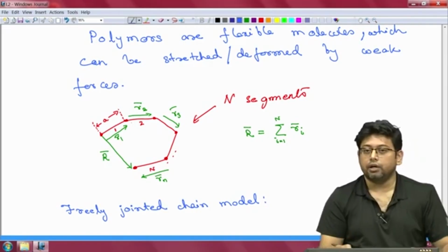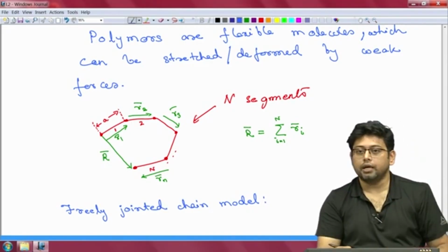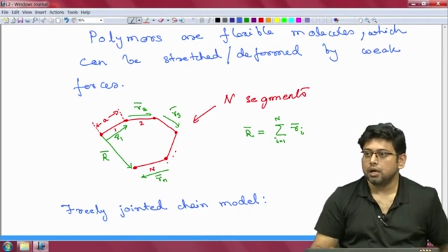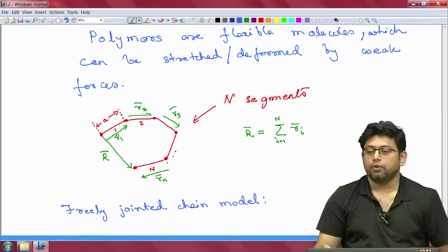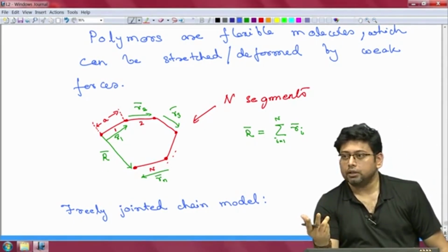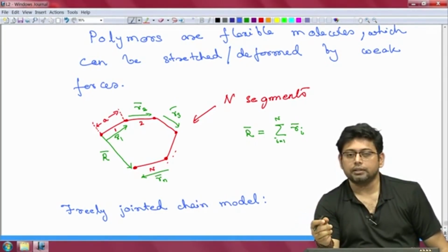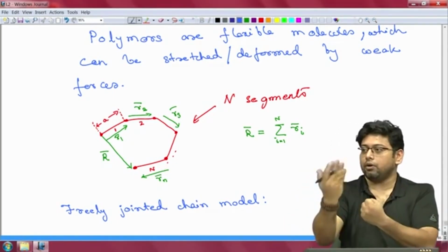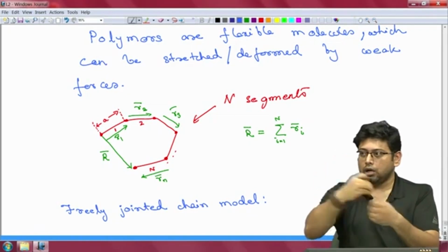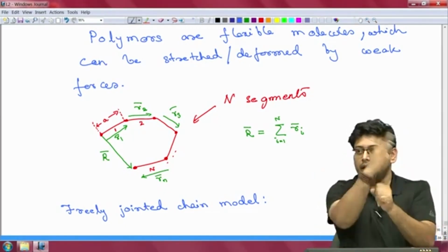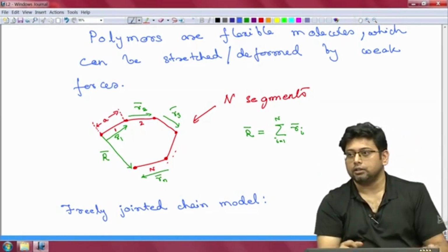And how are these different bonds rotating? Let us say in the case of polyethylene you have the carbon-carbon single bonds and they are rotating because you have the thermal energy which is allowing these molecules to rotate, and how it rotates, keeping that 109 degree angle in that case, is that it can rotate in any way, except that it cannot just collapse back on itself. So, there is one small area which is not allowed for it to visit, but anywhere else it can just keep on rotating.